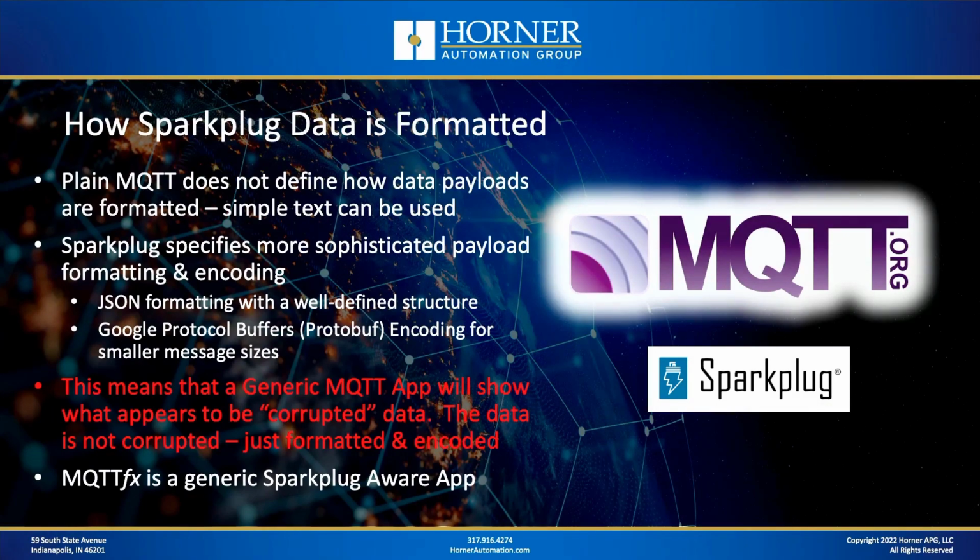So again, if you're going to use any kind of generic MQTT tools as part of your testing on an MQTT system, you're going to have to be aware of that issue. Those tools really should be Sparkplug aware. And there is a very popular tool called MQTT FX that we've used on this channel and that I would recommend. It's no longer free. I think you do have to pay for it, but it is a good test MQTT software client, if you will, or subscriber, and it is definitely Sparkplug aware.